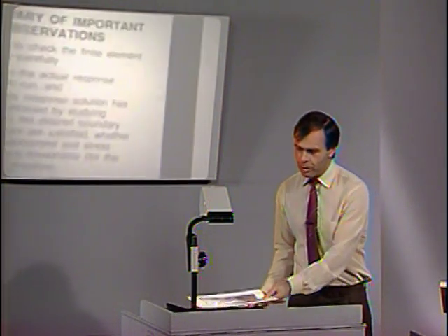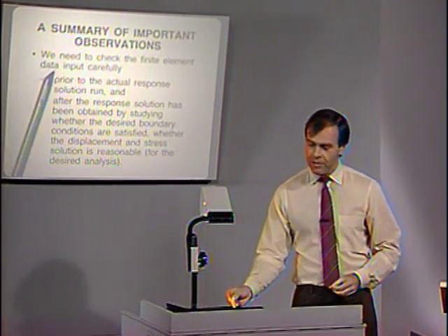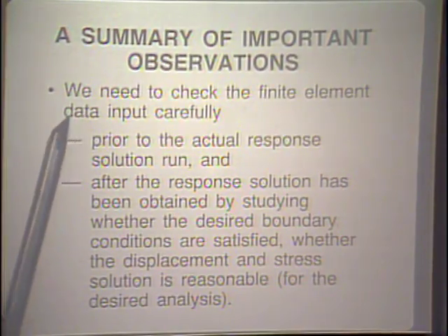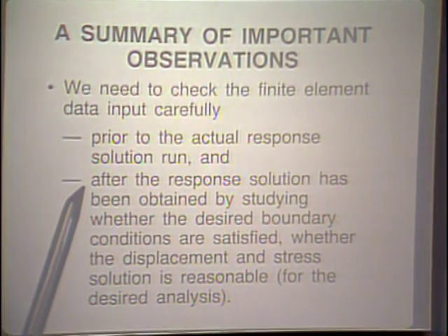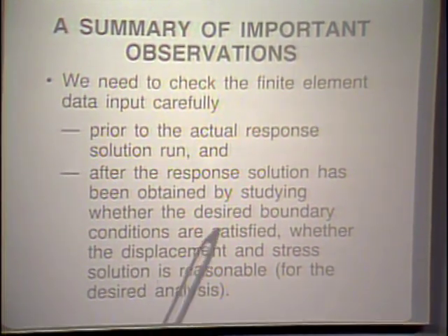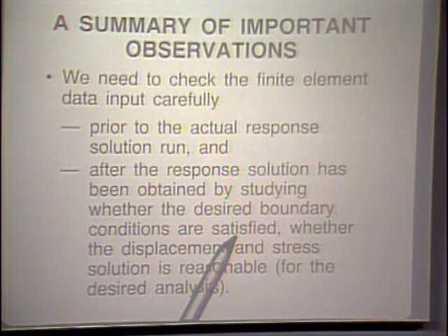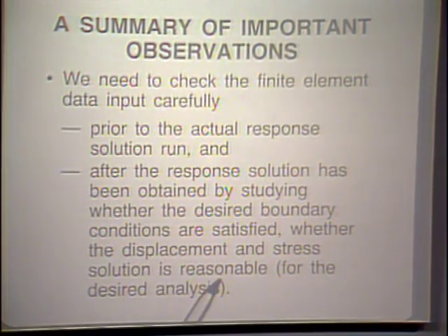Let us summarize some important observations regarding finite element analysis. It's important to check the finite element data, of course, very carefully. The data must be checked prior to the actual response solution. This is done with the preprocessor by plotting the data and looking at it very carefully. And then, after the response solution, you still want to check the input data once more, by seeing whether the boundary conditions that you wanted to impose onto the model are properly satisfied, and whether the displacement and stress solution is reasonable.